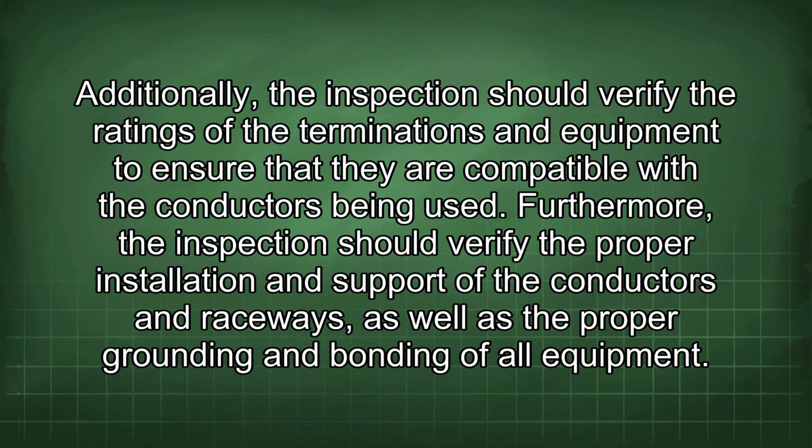Additionally, the inspection should verify the ratings of the terminations and equipment to ensure that they are compatible with the conductors being used. Furthermore, the inspection should verify the proper installation and support of the conductors and raceways, as well as the proper grounding and bonding of all equipment.